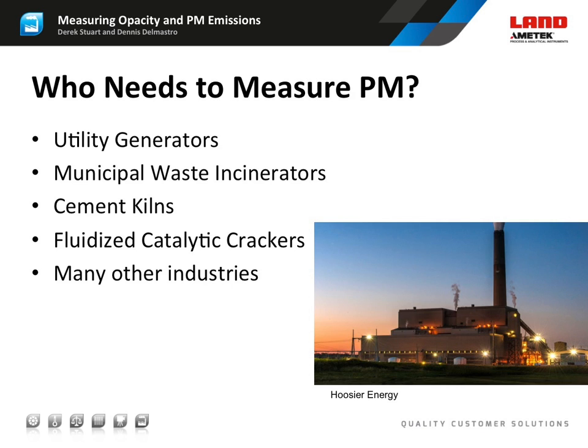PM monitors are used in many of the same applications as opacity monitors, but regulations in some countries or in some industries may specify one or the other. For example, all applications in Europe require PM measurements, not opacity. In the US, power generators have a choice of opacity or PM, but the cement industry must measure PM.